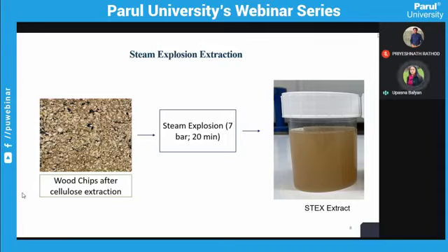For example, what kind of strategy am I talking about? You can use chemical cleaning, in terms of acid and base cleaning, just to remove irreversible and reversible fouling over the membranes.